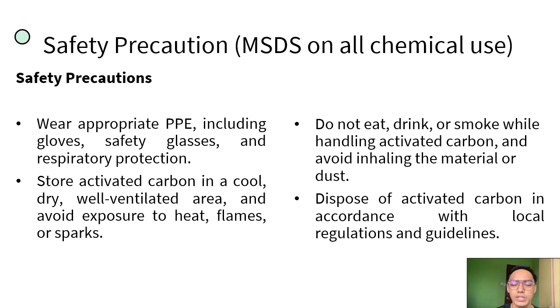Under safety precaution, it is important to wear appropriate attire such as personal protection equipment. Store the activated carbon in a cool, dry, well-ventilated area and avoid exposure to heat, flame or spark. Do not eat, drink or smoke while handling activated carbon, and avoid inhaling material or dust. And lastly, dispose of activated carbon in accordance with the local regulation and guidelines.